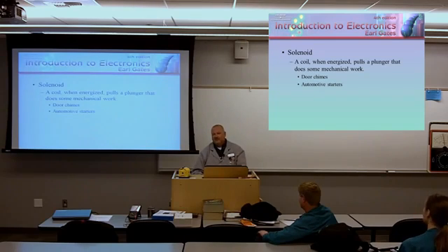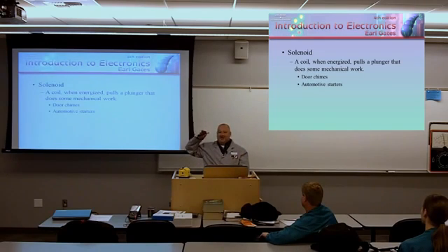Pilot control lighting. One of the things I've been known to do, if I'm bringing somebody that's not accustomed to aviation, is start the approach, flying the instrument approach, following an invisible glide path down to the runway. When the lights are turned off at the airport, it's just a black hole. You're just descending into this black void. Then about a half mile out, I'll dial in the frequency and hit the code. It's a matter of turning my transmitter on and off, five times, which turns it to high intensity. So all of a sudden you're descending into this black hole, and then before you, this runway appears with the chaser lights and everything, and it's kind of a power trip.